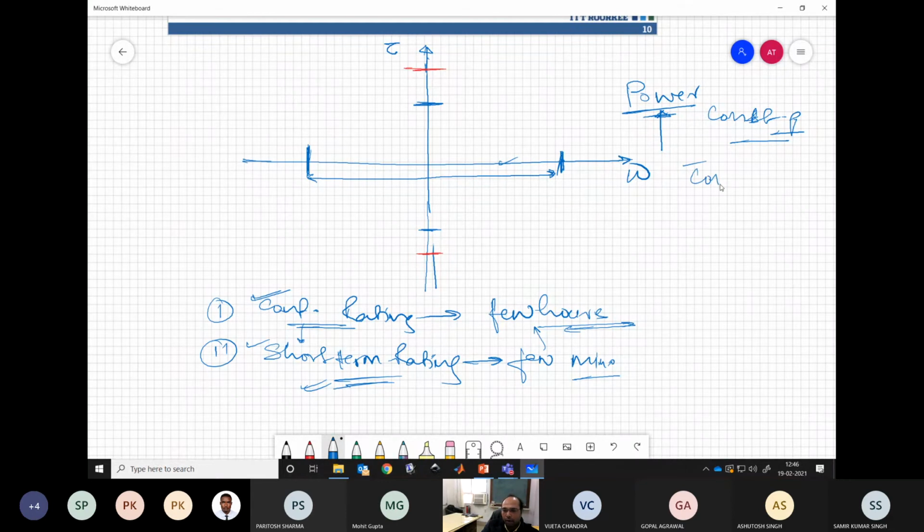So somewhere we fall into the constant torque, or sorry, here the opposite. We cannot have constant torque for the entire range. We must have some restrictions beyond a certain speed, because we will be violating the power limits.